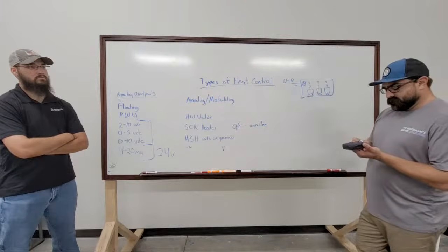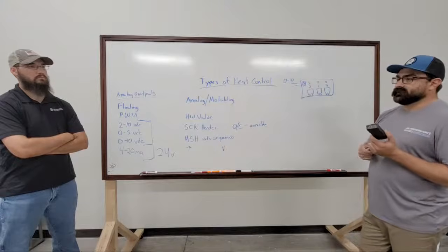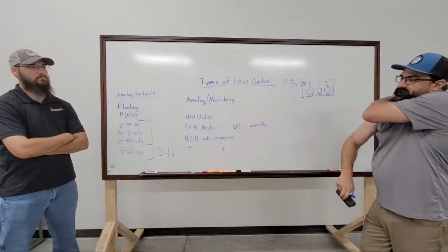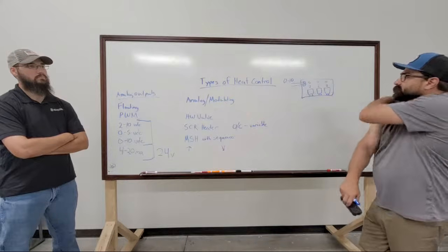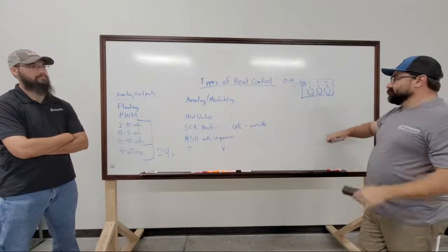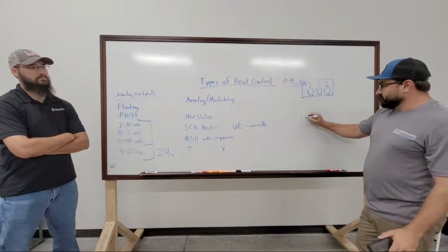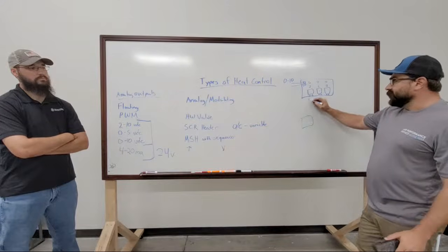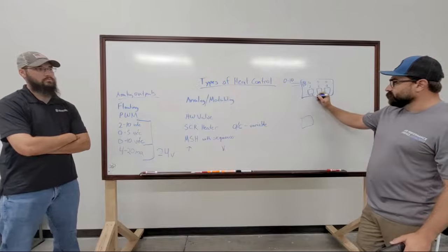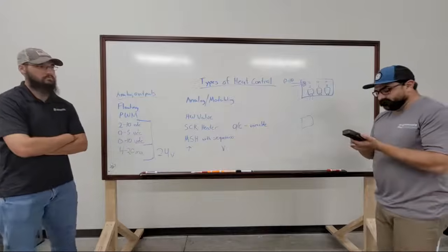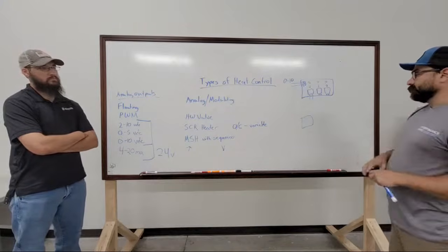You see them a lot of times on outside air handlers and things like that that have big staged heat, where you can't really use an SCR just because they can't take the amp drop. But what you'll get is a big contactor that's running your 480, and then this guy will run like a 120 volt loop through it, going to that contactor, pulling that contactor in. That way your main load is here.